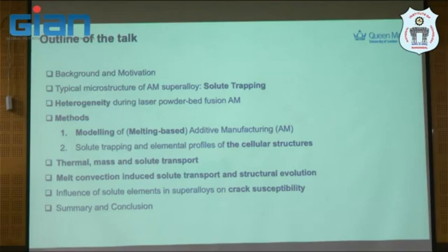Actually, does it happen at the melt-pool length scale? And what is the thermal mass solute transport during the deposition of the nickel-based superalloy we'll show you later? And how this one induced the transport, this one induced the structural evolution, in this case microstructure evolution during printing.